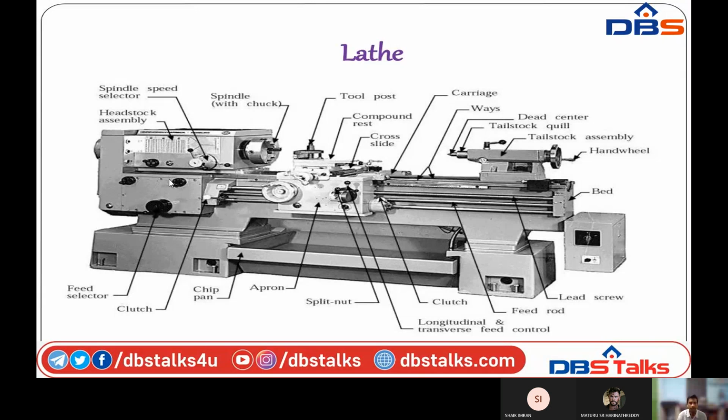Next, in this speed adjuster, we adjust the speeds by changing the gears, using the speed changing lever here. Next, the feed selector. The feed selector is used for changing the feed direction to the left side or right side.